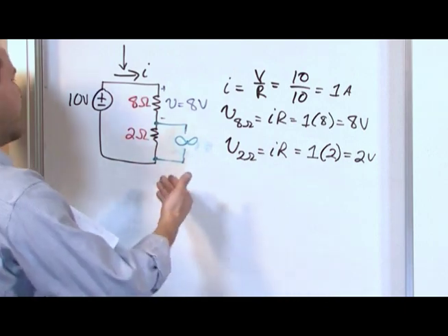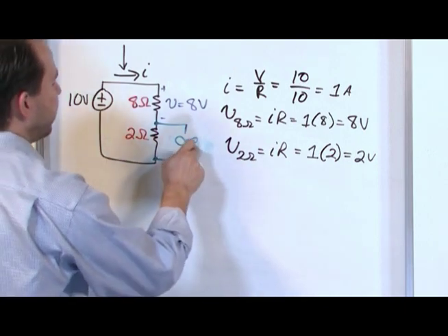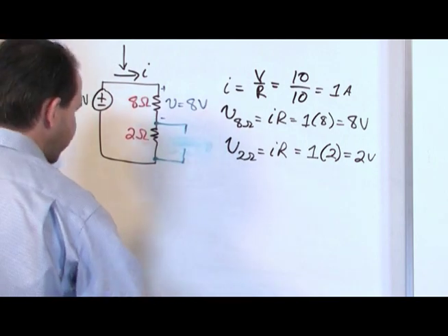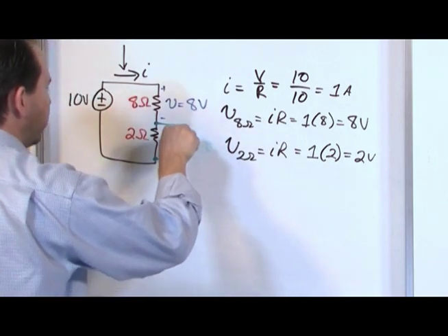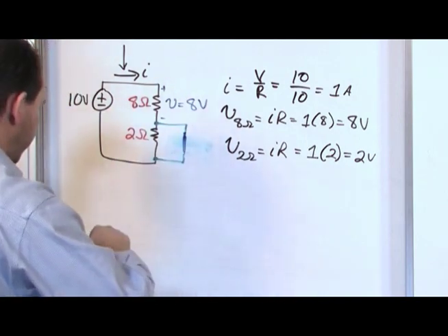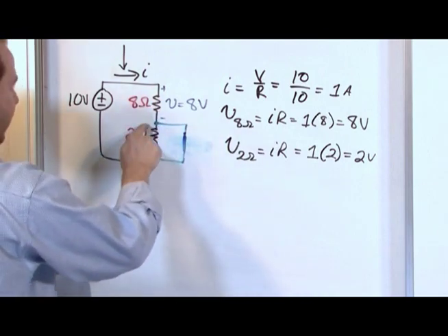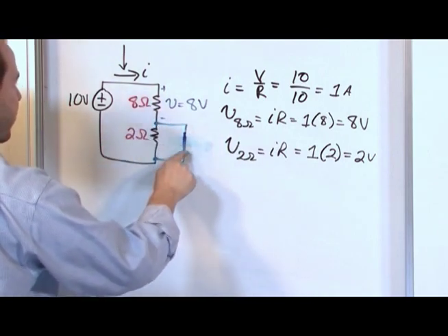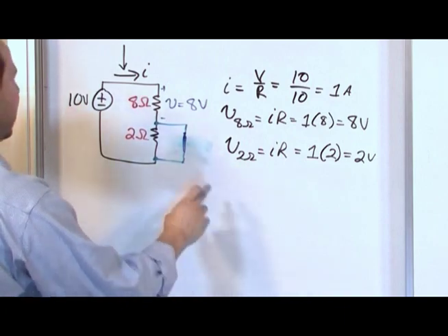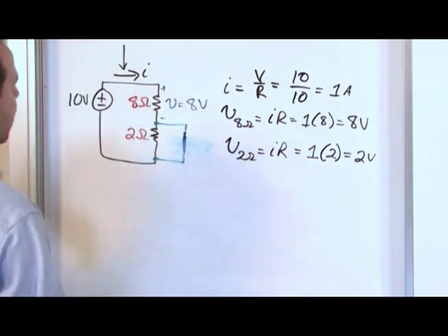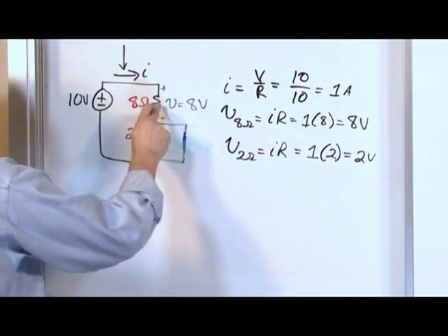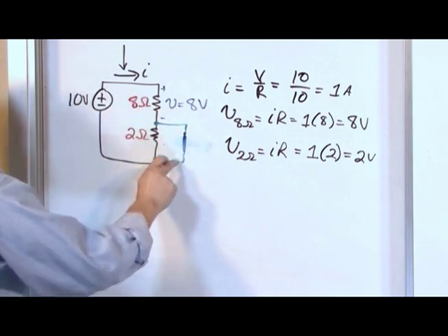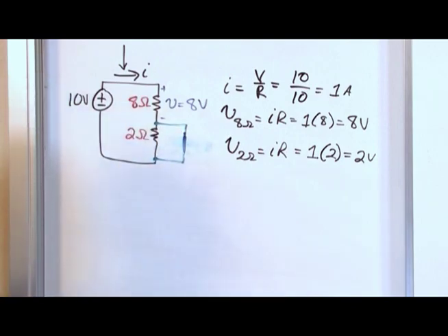If you drive this resistance to a short circuit, what's going to happen? Now it's a short circuit, zero resistance. What's going to happen here? None of the current's going to go through this resistor. All the current's going to go zoom, right around. I've completely altered it. I'm going to get 0 volts over here because I've got no current through this resistor, and there's always 0 volts when you have a wire there. There's no voltage drop across a pure wire.